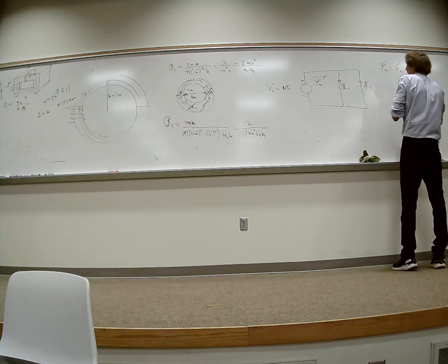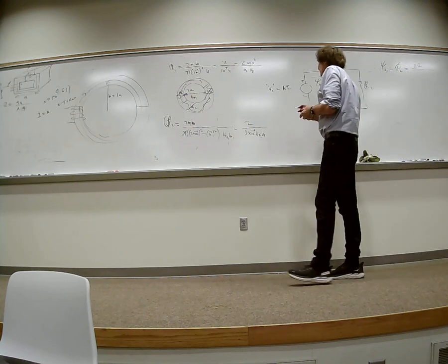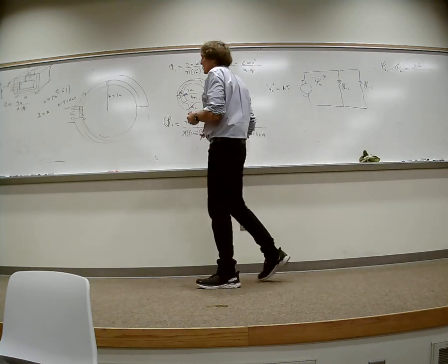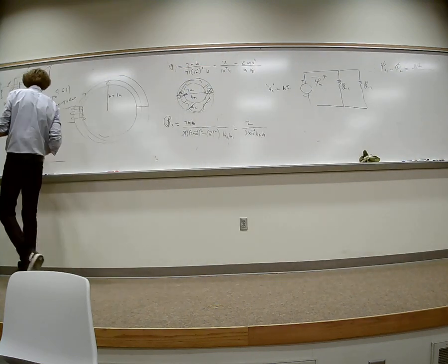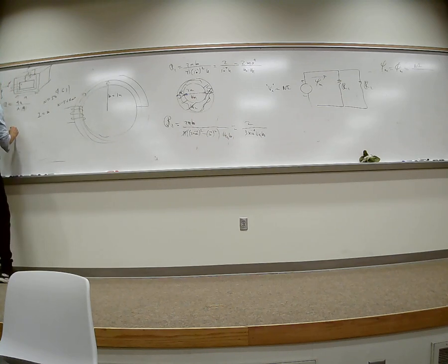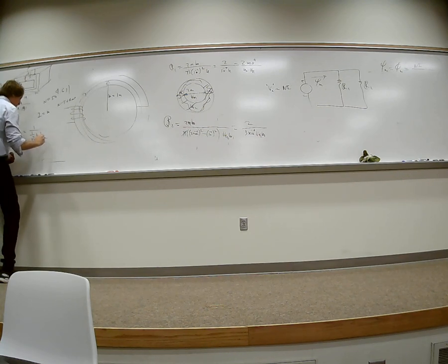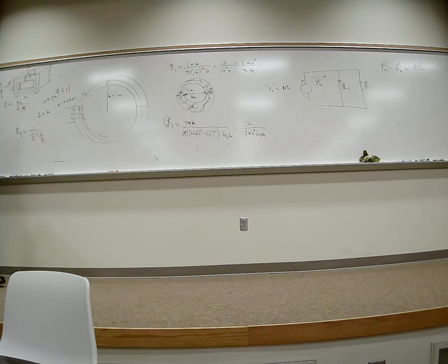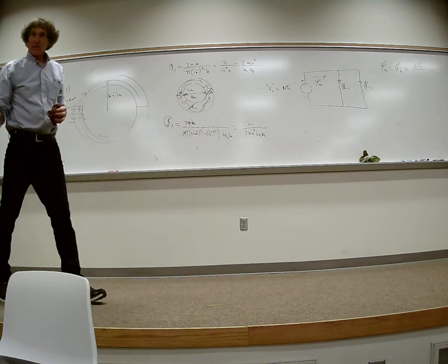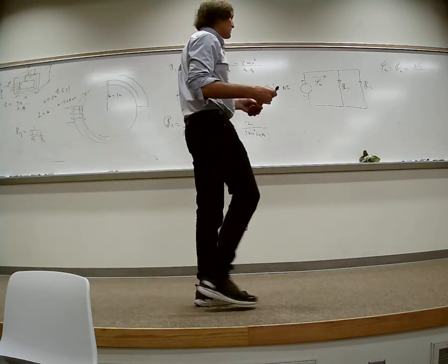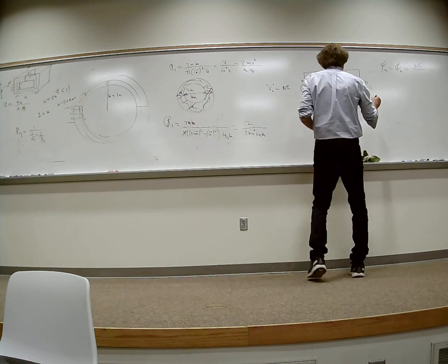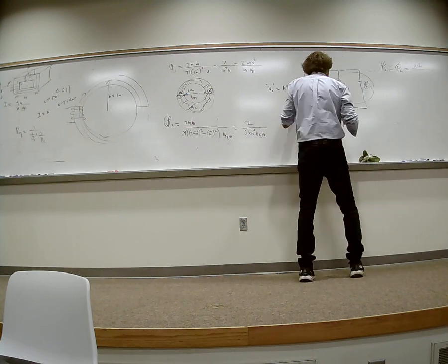And it's divided by the parallel values of those two. Well, if we have reluctances in parallel, the actual equivalent value is going to be 1 over reluctance 1 plus 1 over reluctance 2, just like parallel resistors. Does everybody follow me on that? Class? All right. So come over here, then we'll get the equivalent reluctance of these two.